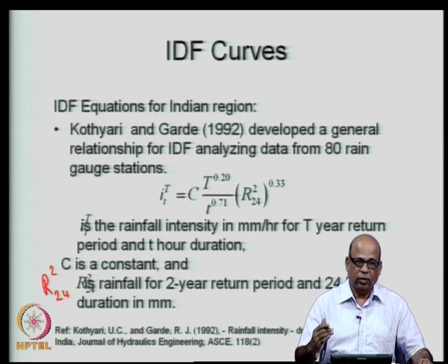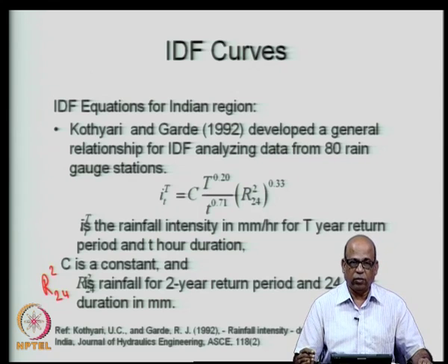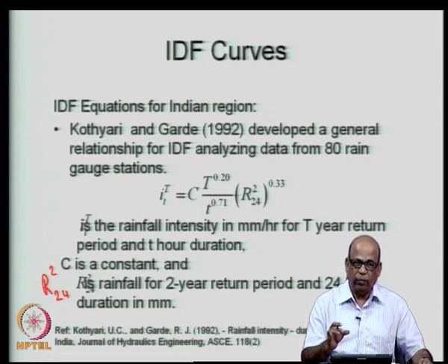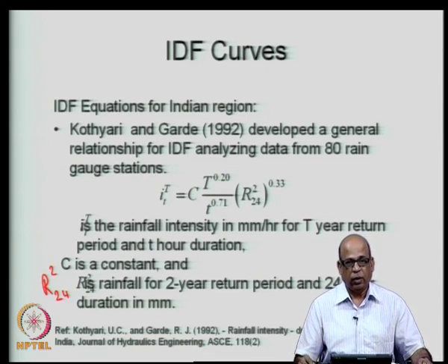If, let us say, every decade you start computing the IDF relationship afresh, then these can be quite different. For certain locations, the intensities that you get for a particular return period and the same duration can be much higher compared to those obtained by the previous IDF relationships.